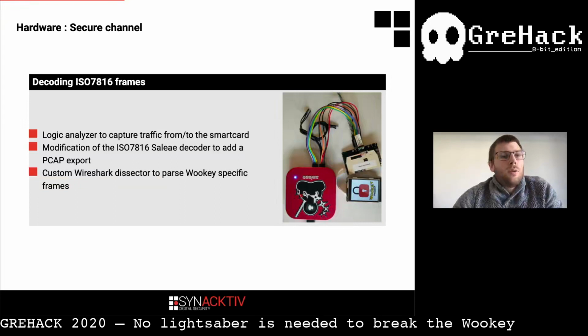Our logic analyzer already has a decoder for this protocol, so we just modified it to export data in PCAP format. We were able to load the PCAP in Wireshark, and in Wireshark we wrote a custom dissector to analyze Wookey-specific frames.